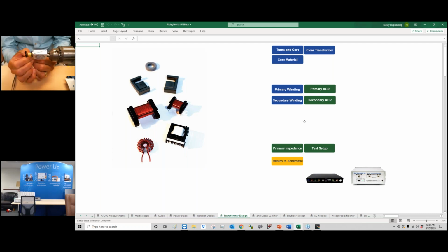Be a little more careful with the bifilar. Cross them over again. Again, if you cross and you create space, you create leakage. Get a truly automated winding machine, this will be no problem. You can also buy bifilar wire where it's already glued together, so you don't have to. It's a little bit more difficult. Lots of wire companies will do that for you. So you can buy the red and green already bonded, ready to wind like this.